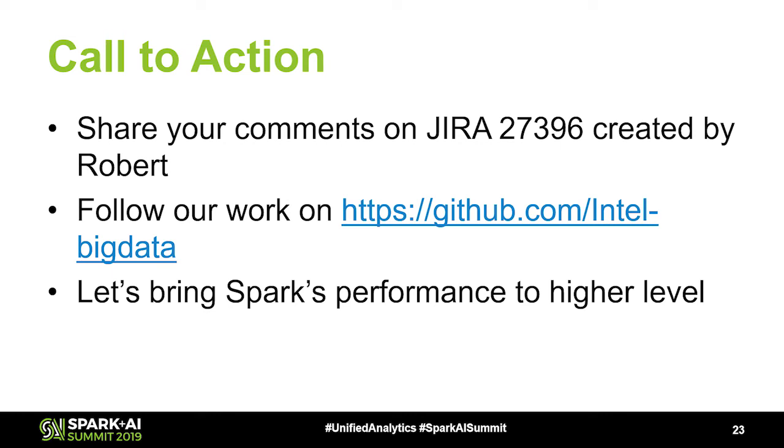If you use Arrow for the data exchange between Spark and the FPGA, do you think the data copy is still the major overhead, no matter what optimization you do? Yeah. When we break down the elapsed time of the FPGA offloading, we see that the data convert is the biggest overhead when we offload. I remember the FPGA working time is about 12 milliseconds, but the data copy and the data convert takes about 36 milliseconds.